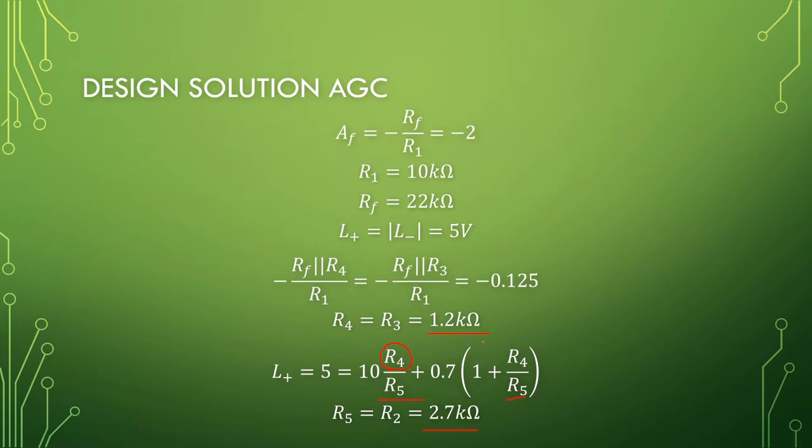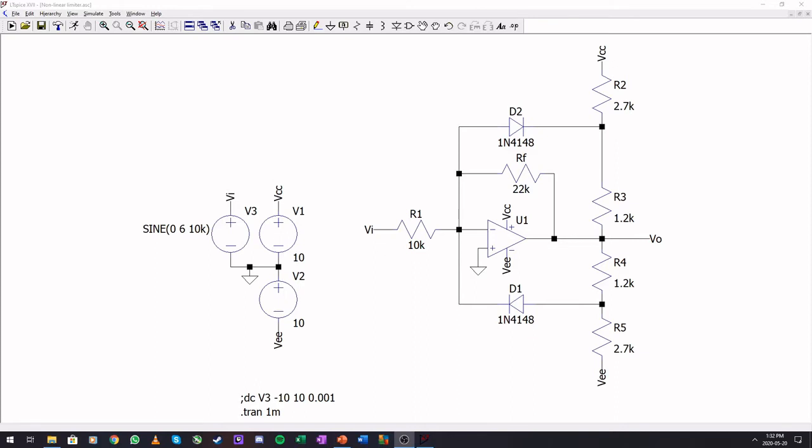So let me jump into the simulator and show you that this does work. So here is our non-linear limiter, and I built it using two signal diodes. And first off, I'm going to run it with a 6 volt sinusoid at 10 kilohertz and see if it actually does limit the circuit. The signal that you're going to see is not going to be so pretty anymore. It's not going to be pure sinusoidal because this is meant to bring oscillators into check.